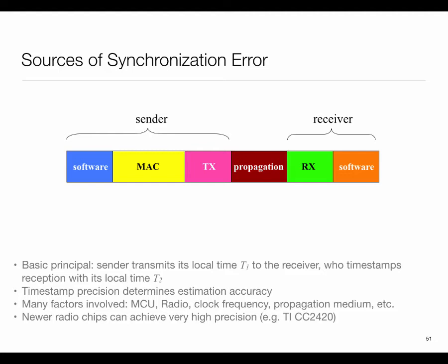Now that also is a big assumption, because the algorithms in Tx and Rx usually involve some coding and stuff like that. So it's not as if the delays through them are necessarily constant. The delay may vary a little bit. So the best situation for you is when you timestamp as the bits are actually going to the antenna and then actually arrive at the antenna, or the two ends of the wire.